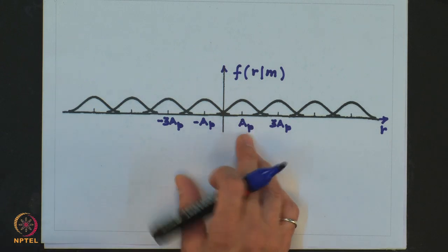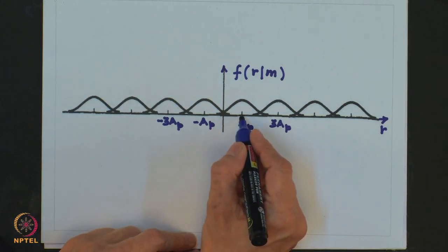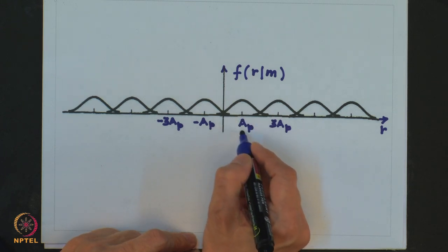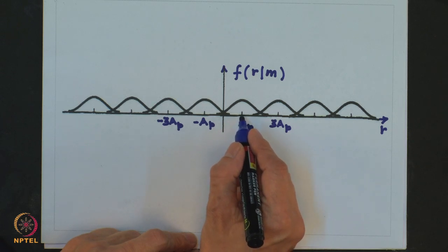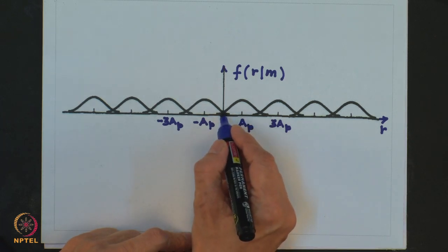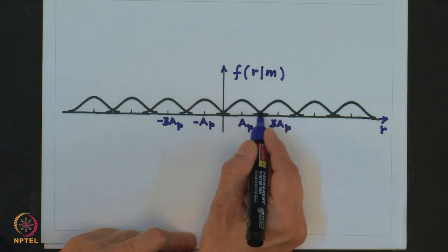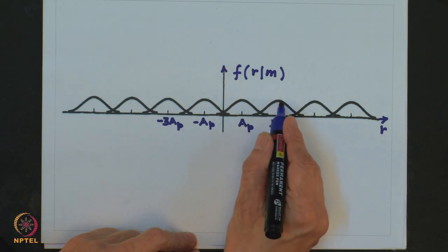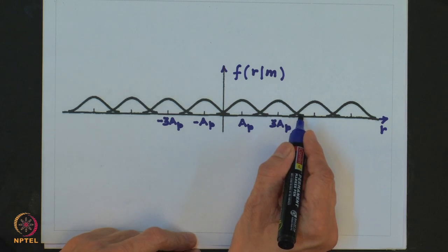Assuming Gaussian noise, if I have transmitted the message corresponding to Pt, then the conditional distribution of the output given that the message was Pt is given here. This is a Gaussian distribution. Similarly, when my message signal was 3 Pt, then this is my conditional Gaussian distribution.